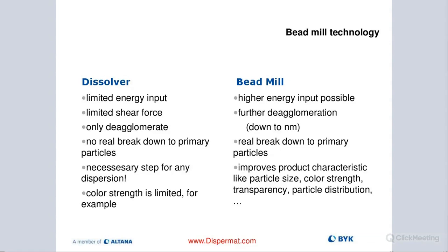It's really almost impossible to do without some sort of media. And it is a critical step for any dispersion process that you properly pre-disperse. If you don't pre-disperse and you go straight to a media mill, let's say you start out with 100 microns or 80 microns, and you go to a horizontal bead mill, for example. You have a screen, depending on the manufacturer, or you have a dynamic gap, and there is a size that basically allows for the beads to stay back in the milling chamber and everything to circulate back through the milling chamber until you're reducing your particle size to the appropriate size.